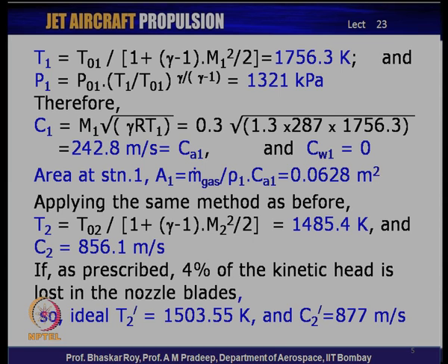We are using the isentropic flow condition because, as we have done before in thermodynamics, at any particular station, conversion from static to total or total to static can be done simply by using the ideal isentropic relations, because at that particular station it is assumed that the flow is undergoing an isentropic conversion. That is an assumption, of course the theory, and we can always invoke it at a particular station.